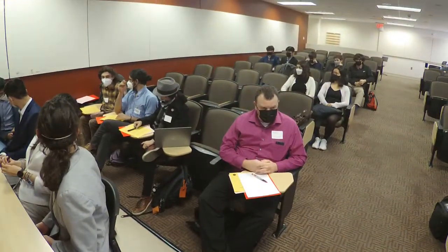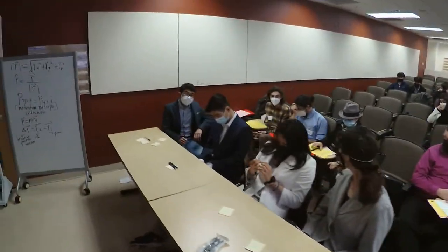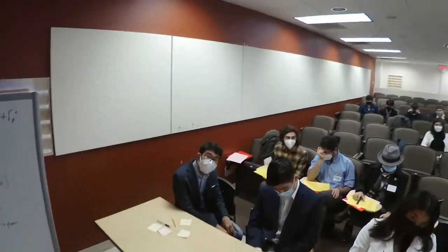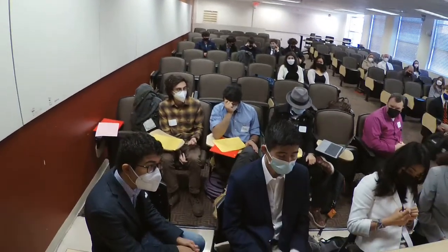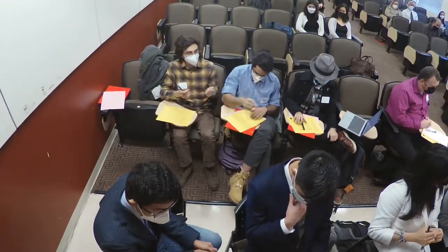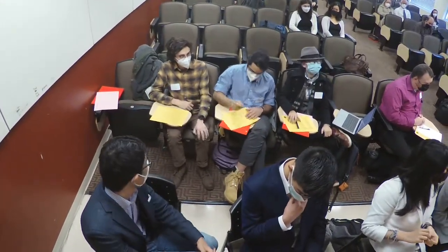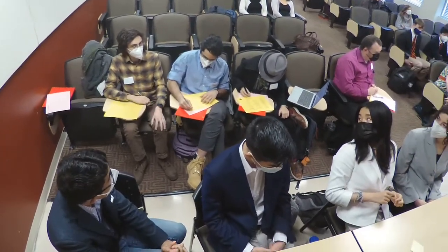Okay. You guys down there, do you have a question? Yeah, so question to the presenter. In terms of this drag coefficient, or the drag forces in general, you sort of are attaching a single drag coefficient for each trial. Do you expect this to be a single homogeneous property within the French press, or would you expect any variation, maybe with time or where it is within the water?